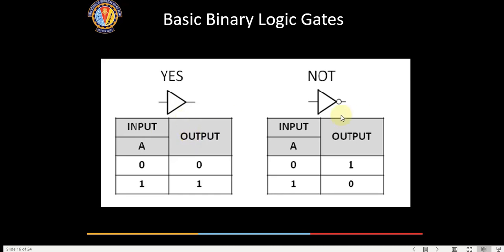Similarly, you have a NOT gate. A NOT gate just inverts 0 to 1, 1 to 0. This is the logic representation. Like different families, it will be different. For a TTL gate, 1 means 5 volt. For a CMOS 45 nanometer, 1 means 1 volt. So these are only logical expressions, logical states 0 and 1.